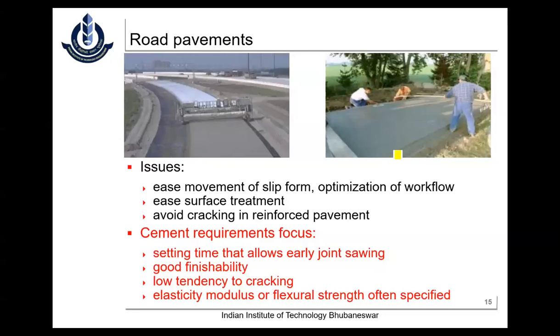But my suggestion is, whenever you want to use a PPC cement, ensure that the blending is around 30% or 35%, so that it will really give the right performance as far as durability is concerned. Ultimately, that is the prerequisite everywhere. The performance is my requirement. The durability is my ultimate requirement. We need to look into the overall performance of concrete. Yes, the performance of the concrete is the ultimate goal of any cement manufacturer.